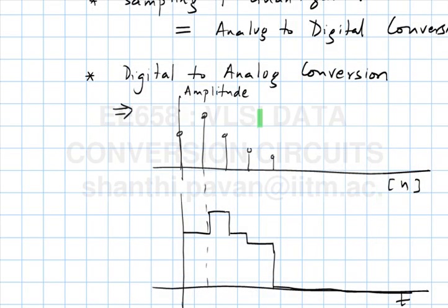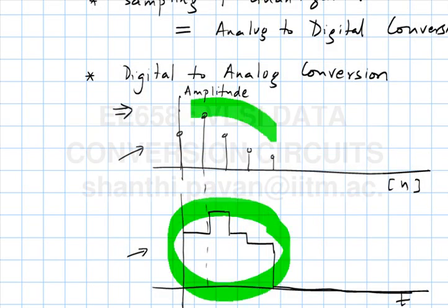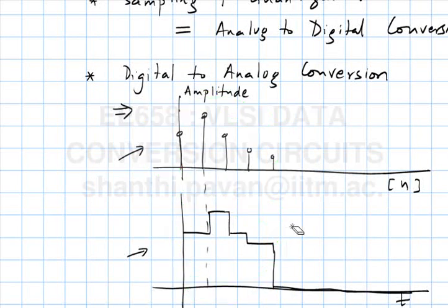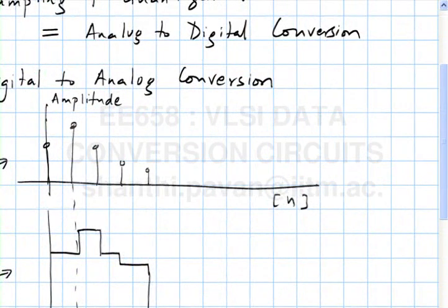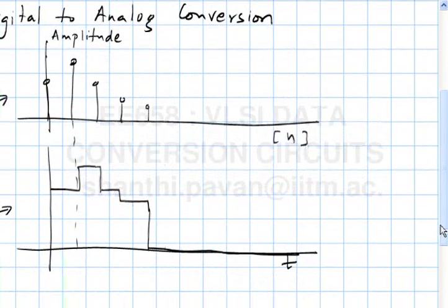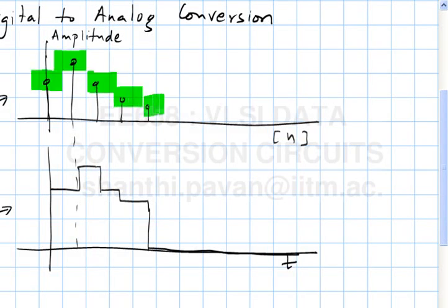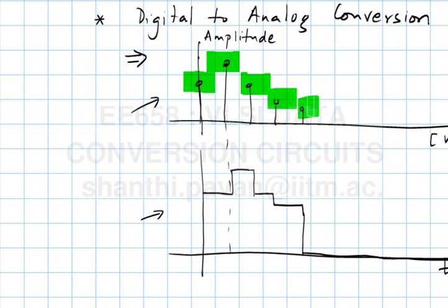So in other words, while you understand that this is discrete time and this is continuous time, you see that this waveform here has some semblance to the set of discrete numbers. A gadget which accomplishes this objective is called a D2A converter, and as it turns out, these amplitude levels are actually quantized simply because they all depend on the register lengths inside a DSP.